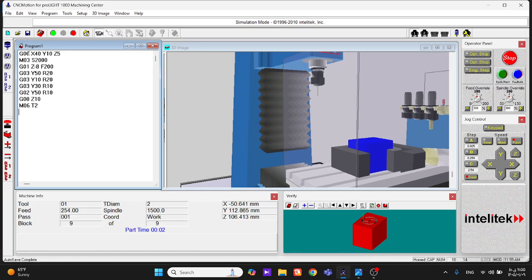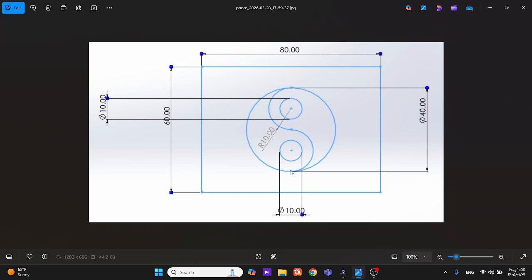Same scenario: G00, X40, Y10, and with Z5. Well, this time I will make it Y20, because I want to shorten my coding. You can come here and again come here, but is it necessary? No. You can go directly to this center. So what is this position?